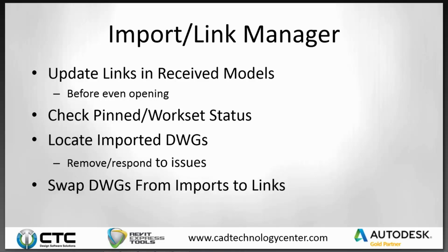And even as a contractor slash designer, there are a lot of times when you have to keep updating links from models that you receive. The Import Link Manager can actually help you update those links even before the model is open. It could be not even open yet, just sitting there on your network, you just downloaded it from the FTP site, and you want to update those links before the model's open so that when you open up that model, those links are up to date and ready to go. And Import Link Manager can actually help you with that process.